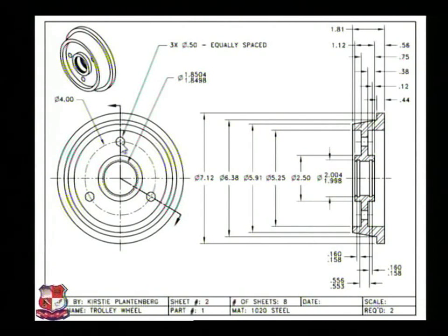But what will you do if there are 3 circular holes? You can see here 1, 2 and 3. If you cut this straight away, a hole may not be there. So in that case we have to use this inclined cutting plane. This is a divided cutting plane.